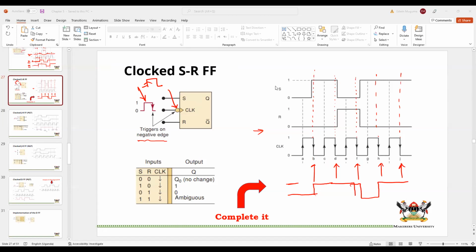So we were talking about the SR flip-flop. We are going to continue today with a couple of other flip-flops, but what I really emphasized is that these are synchronous devices, in the sense that they wait for the clock to happen before something happens at the flip-flop. So they are synchronized with the clock, so to speak. And these flip-flops are edge triggered.